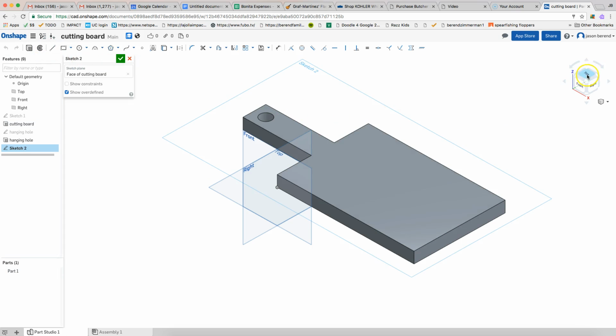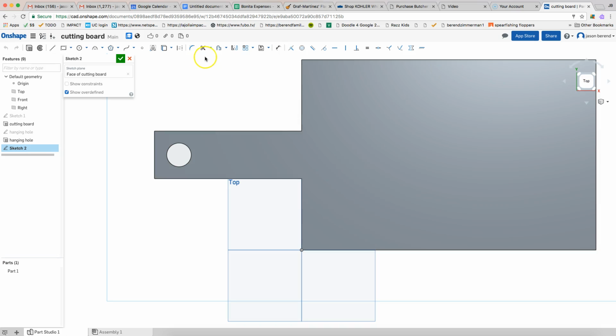And I'm going to zoom into the top. There's a command over here called offset. And I'm going to click on this top edge here. I'm going to hold down the left mouse button until this becomes, say, 0.5. I'm going to click on this left edge one time. And if you click around, these lines should come up.